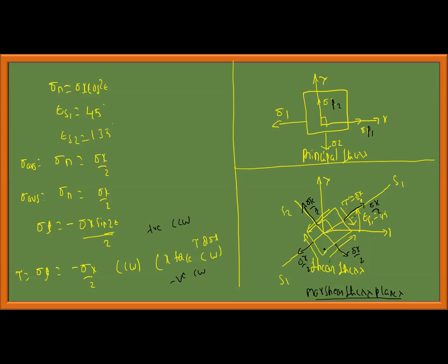Okay. Now, this is about principal stress. For shear stress, with respect to theta s, I should always rotate with respect to the x-axis. If theta s is minus 45 degrees, it would be rotated in the clockwise direction, like this.